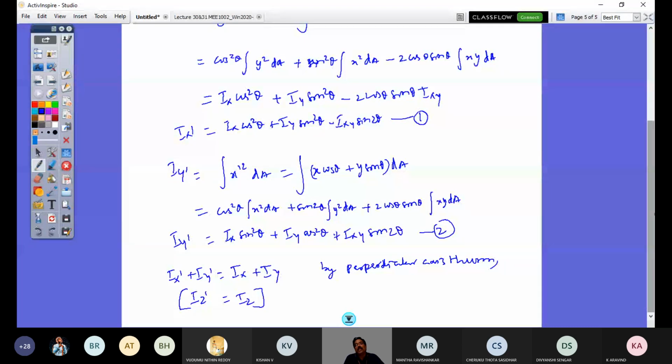As the section orientation is changed, your stress values change, so the stress value is a combination of normal stress as well as shear stress. This is all analogous, and when you do the next course you would see similar analysis and derivations for stresses and strains as well.